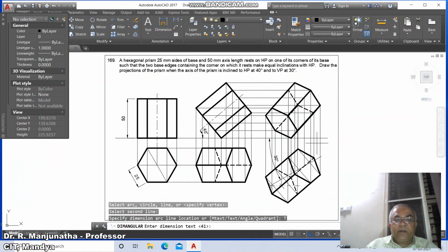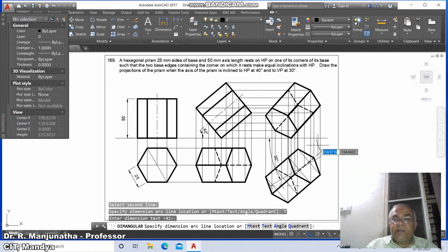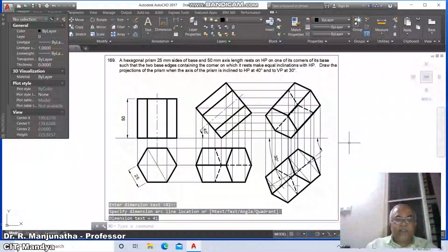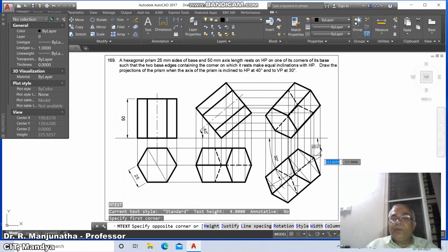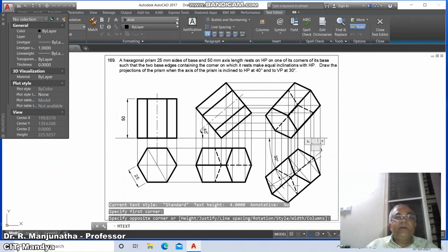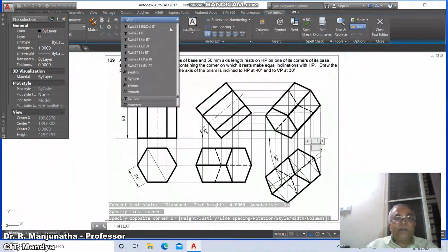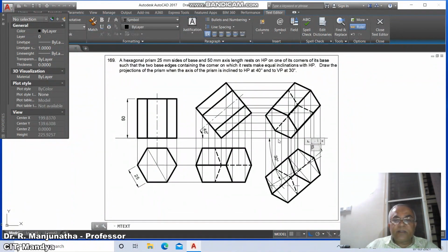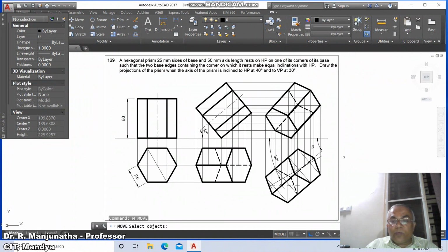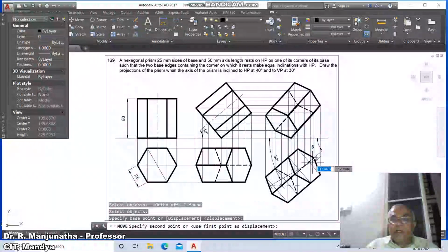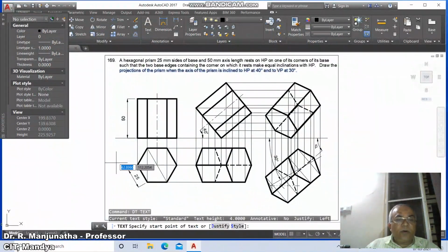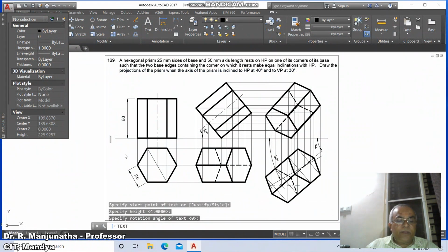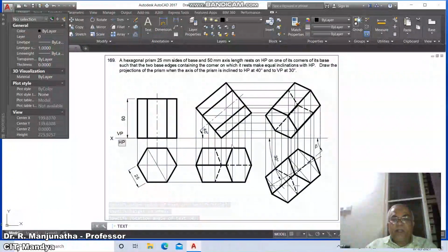So here give space and enter, then here you type, take this as mtext, type MT, select this as the window, then you just click on symbol, take this as beta, small letter b, then go to move, switch off the ortho mode, take this and place it here. Text, go to text, click on caps lock on, type X, type VP, type HP, and here type